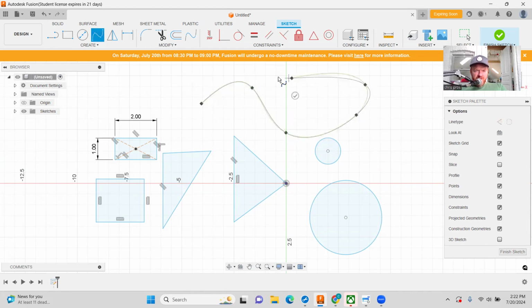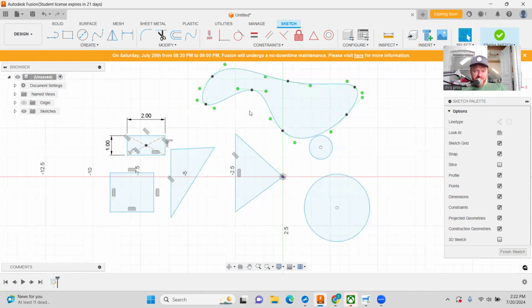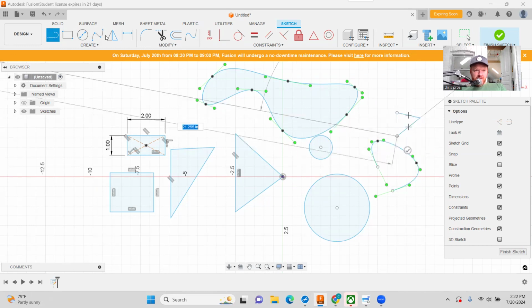One thing to know with the spline tool is when it's exited, press escape first. Otherwise, you might lose your spline, or connect it with a line until it's a complete shape. So for example, if I'm making a round one and I come over here and click, I guess it did work. Otherwise, sometimes this disappears. If this disappears, just redo it, but make sure you either click on the line tool or click on this check mark first, and that'll complete the spline.